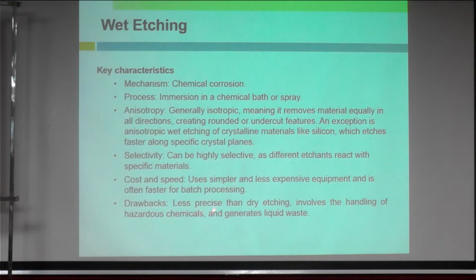Drawbacks: less precise than dry etching, involves the handling of hazardous chemicals and generates liquid waste. So basically, in order to avoid contamination, for example, the chemical can only be used once or twice, then we have to replace it with a new chemical. And also that will become waste, liquid waste, and the chemicals used are always hazardous, such as hydrochloric, sulfuric acid, etc.